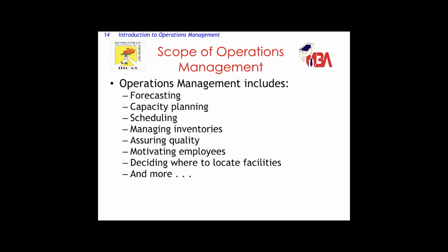Now, the plant location is based on certain factors, because when you want to start an industry, there are certain factors of production. So you will be looking into those factors of production. The land availability should be there, the cost of land should be less, labor availability, raw material availability, power availability, support available from the government, financial institution support, whether it is in a backward area, whether I can get some sort of benefit from the backward area given by the government. So all these factors are going to influence where I'm going to locate the industry.